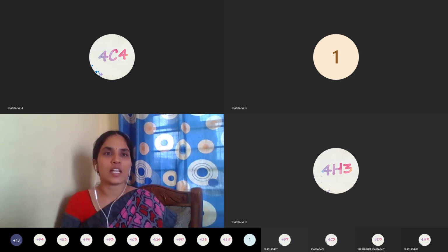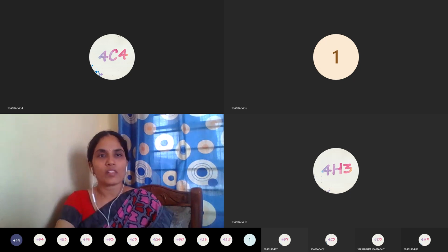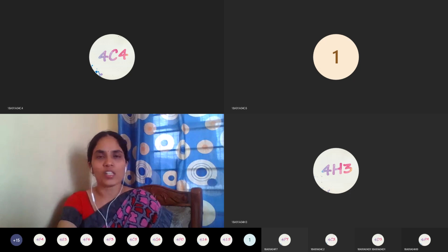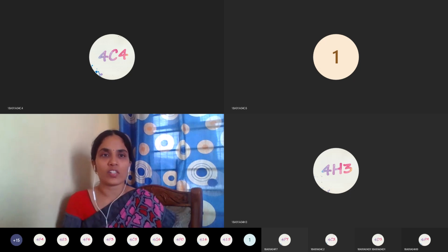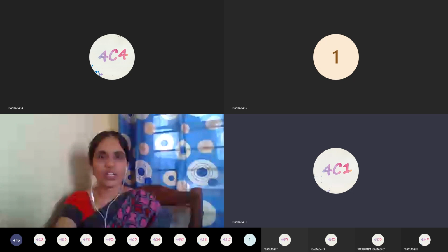Now, all of the students, please observe the three keying techniques shown here. The first row mentions ASK, FSK, and PSK, the three techniques which you want to compare. The first comparison is based on the definition and general expression. So first you define in terms of its definition, like you know the definition for ASK, FSK and BPSK. ASK is the keying technique in which the amplitude of carrier will be varied.